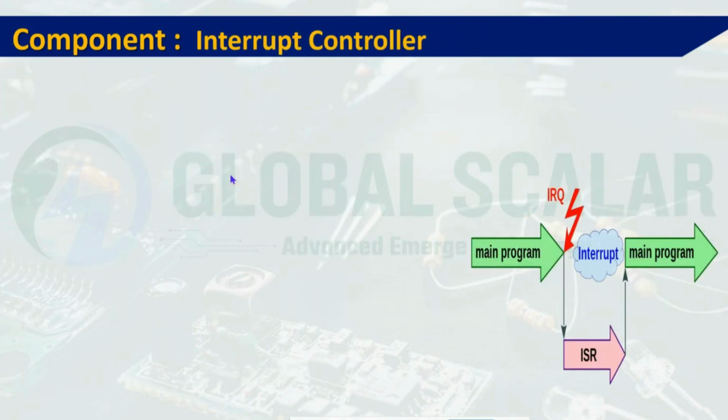And we have the interrupt controllers. So interrupt is basically a disturbance created towards the hardware or software. The microcontroller supports interrupts, which allow the device to respond immediately to external events. So whenever the interrupt occurs, the main program will be suspended temporarily, the current task will be halted, and whichever interrupt has come takes priority.